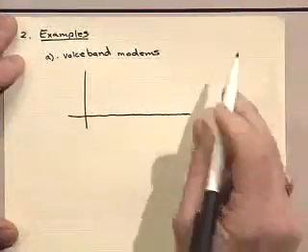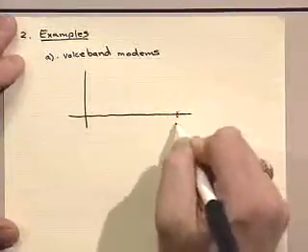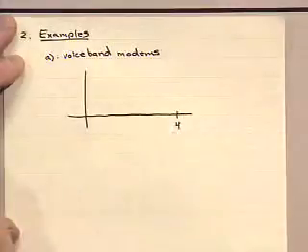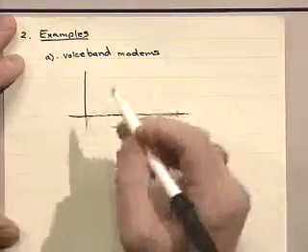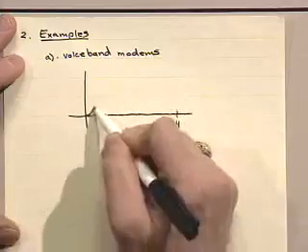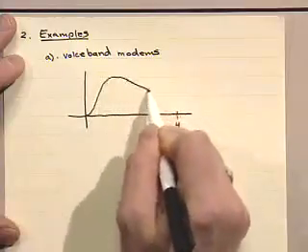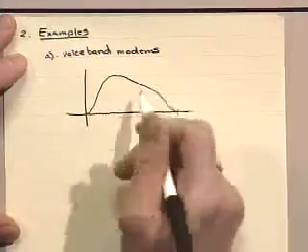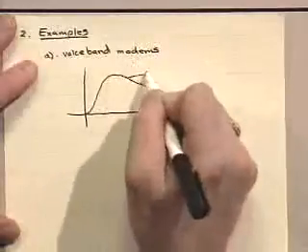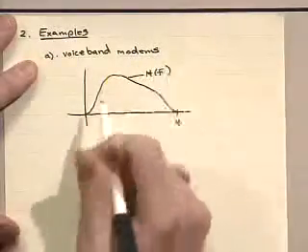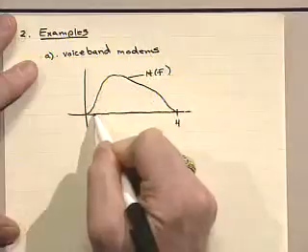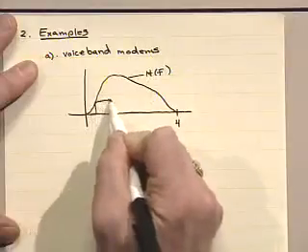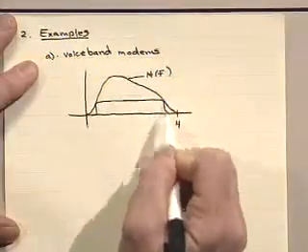But that voice band channel, that telephone channel that's used for one of these dial-up modems, is not a nice flat channel. Kind of looks like this. And so that's your H of F. And of course, they want these modems to go as fast as they can, so they try to stitch a QAM signal in there.